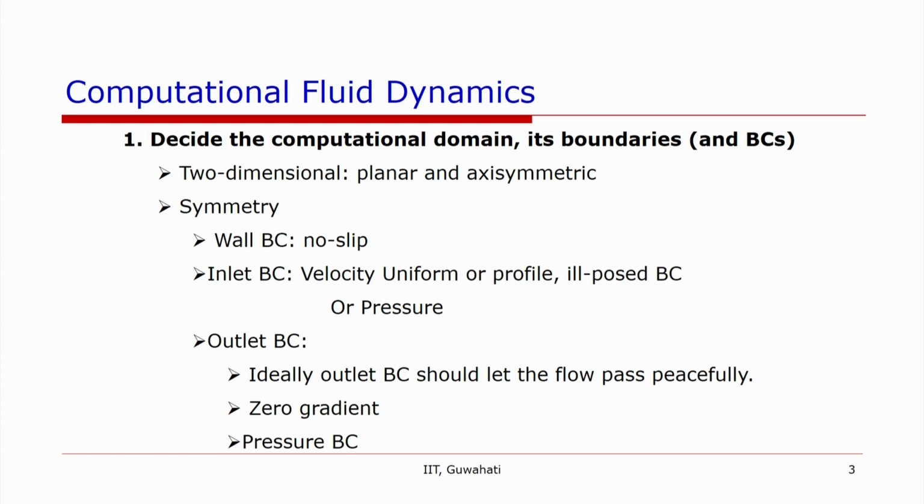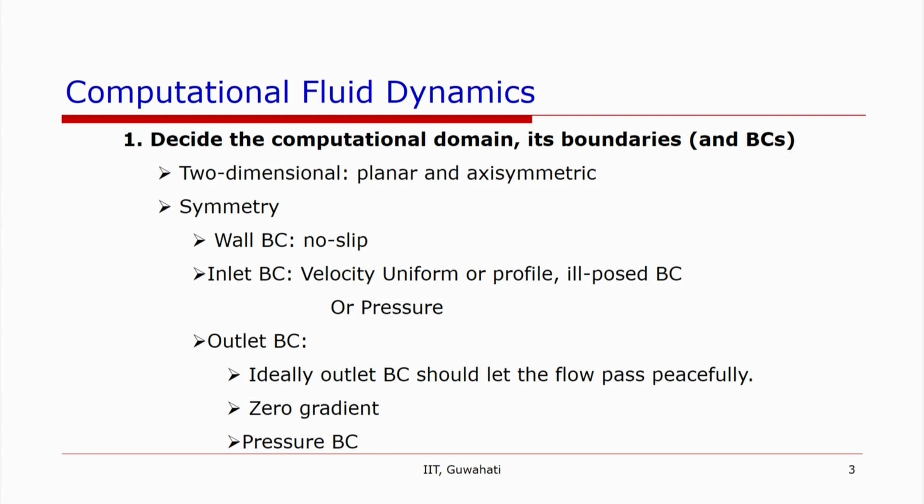when you solve a fluid flow, first you need to choose your domain of interest, or the computational domain, and in commercial software you need to create a geometry for this domain. Then we already have the system of equations. So, if our flow is incompressible and isothermal, then we just need to solve the mass conservation and momentum conservation equations.